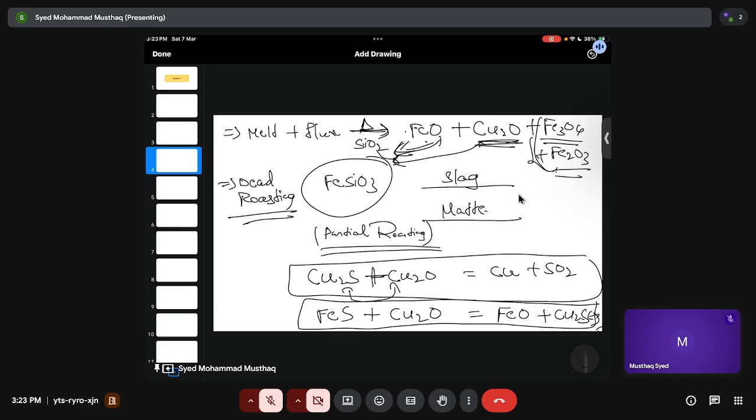So the first thing is that you need to burn more energy, and that will stress the converting process. There you need to oxidize iron also, so that the iron will get picked up. Once you have your melt, you are trying to purge oxygen so that whatever iron sulfide is there gets converted. So instead of stressing everything on converting, I will draw this.